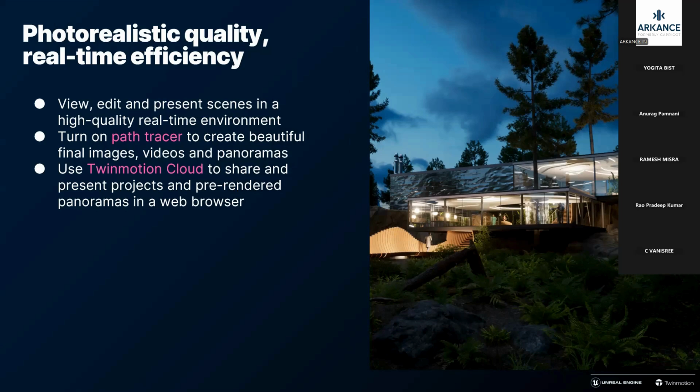Just for an example, if I have a swimming pool, it has certain reflections and refractions on the water part. Once it falls onto any surface, you can also get an idea of how it will have an impact on the facades as well, how it will reflect there too. So that's the main reason to open the path tracer, so that we can get all those reflections of either materials or the surroundings onto any part of it.